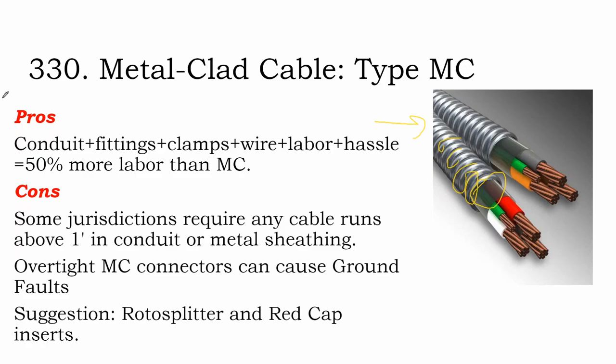And so you can get it in a 1,000-foot spool if you want. Generally I am measuring the runs between the rooftop through the attic and down to wherever the inverter is, and I'm buying enough metal cable to make that run, and I'm just pulling it through the attic and strapping it up to the top of the attic. Not within an inch of the roof, but up at the top in a nice orderly way, and that avoids having to build a conduit run.